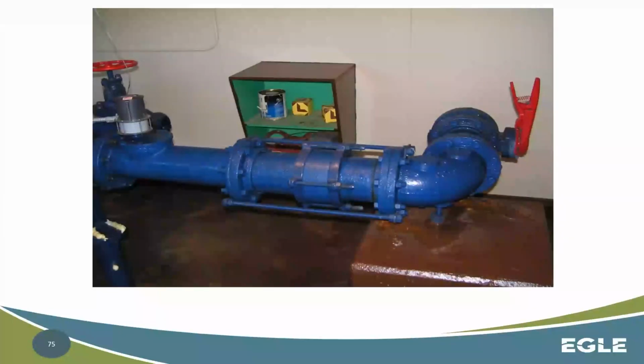Okay. So a few things are going on here in this picture. You have this mechanically restrained portion here with these rods. You also have a slip joint here that we had mentioned earlier. So that's that outer piece of piping here, and there's probably a gap right in here. And then it's tied together with the two gaskets and features right there. Okay. Coupling, slip joint, whatever you want to call it.